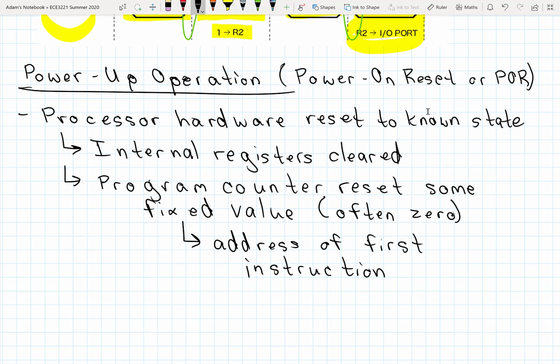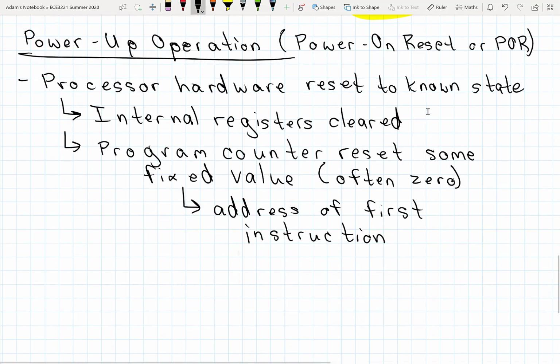At address 0, there is simply a go-to instruction that just jumps the program counter to the location where all the actual instructions are located, and that's often configurable in your development environment to allow you to set up a system. There'll often be a default configuration that locates the code at a specific spot in memory. Sometimes that can be configurable when you get into some more advanced development.